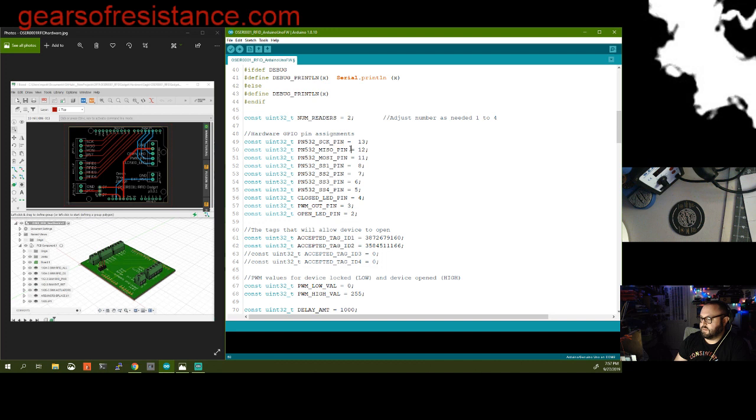I always end everything underscore pin, underscore pin, underscore pin, just so I know, okay, this is a pin. Same thing, don't want it to ever change, being explicit. So, the serial clock pin for the PN532: each board has at least 4 pins, each reader, and all the boards share at least 3 of the pins. Serial clock, master in, slave out, master out, slave in.